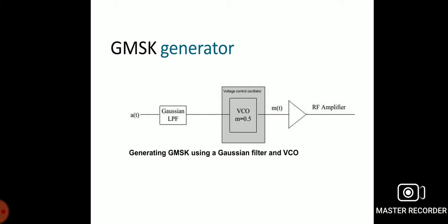transmission using the I and Q modulator method is widely used. What is I and Q? It is in-phase and quadrature modulation. The quadrature I and Q modulation is an effective method to eliminate the synthesizer shortcomings, and also the synthesizer unit is used for GMSK generation. There is a problem that it does not respond to low frequency. Consecutive ones and zeros may not be recognized by it. This problem of allowing only the high frequency signal is overcome in the quadrature I and Q modulator.